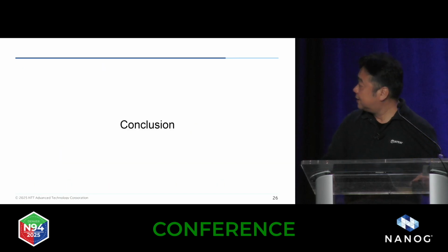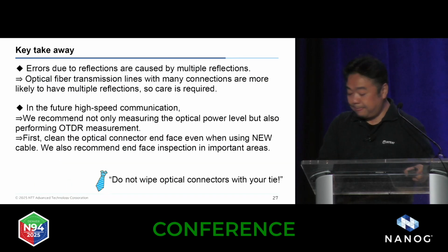So, the conclusion. Remember that multiple reflection can be the cause of communication errors. And also remember that measuring the power level alone might not solve the problems. And always clean the optical connector before use.